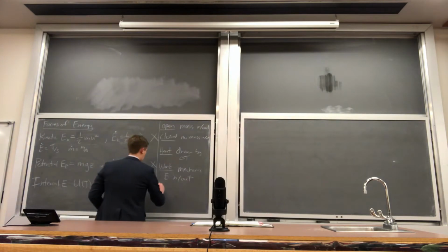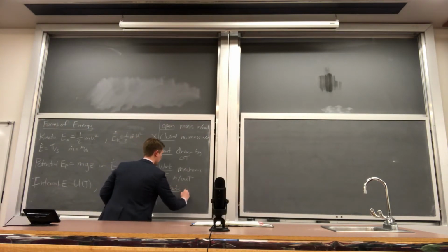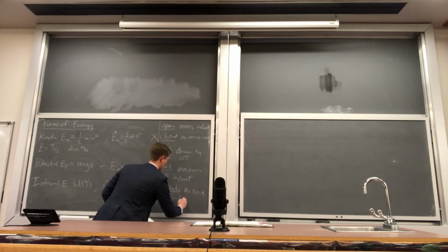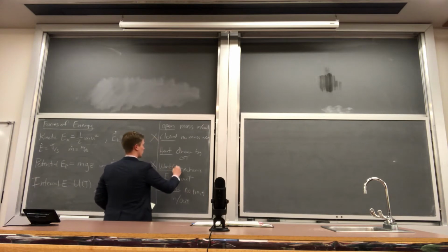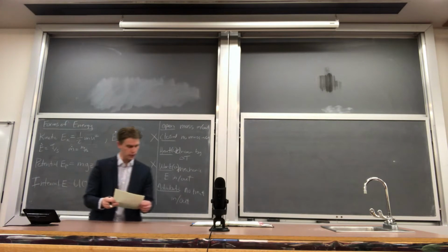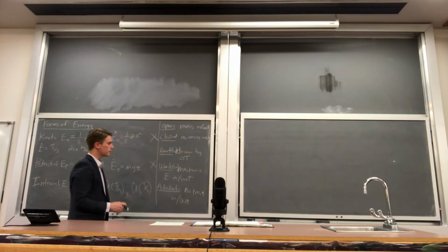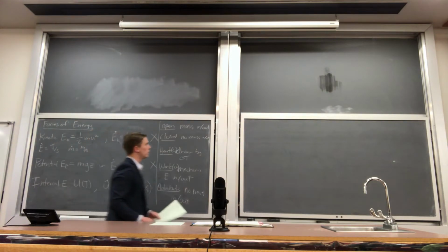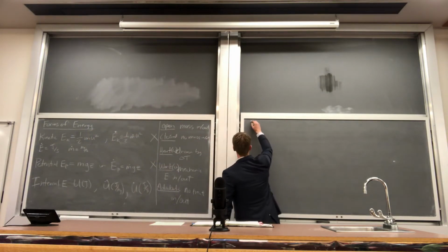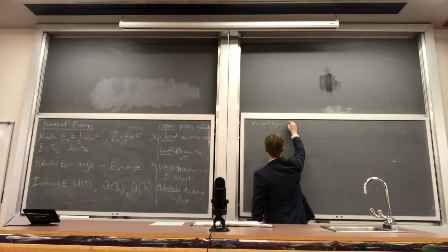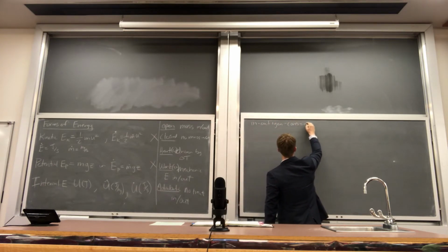And lastly, adiabatic. And this is no heat in or out. So work, we have as W, heat is Q. That's a pretty universal notation. So let's go back to our general balance equation. In minus out plus generation minus consumption is equal to the accumulation.